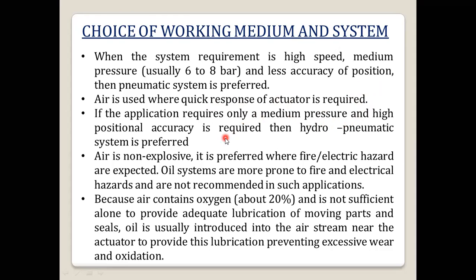So if we want high positional accuracy, then we will use the hydro-pneumatic system. Air, we know, is non-explosive, so it is preferred where fire and electrical hazards are expected. Oils, we know, are more prone to fire and electrical hazards.